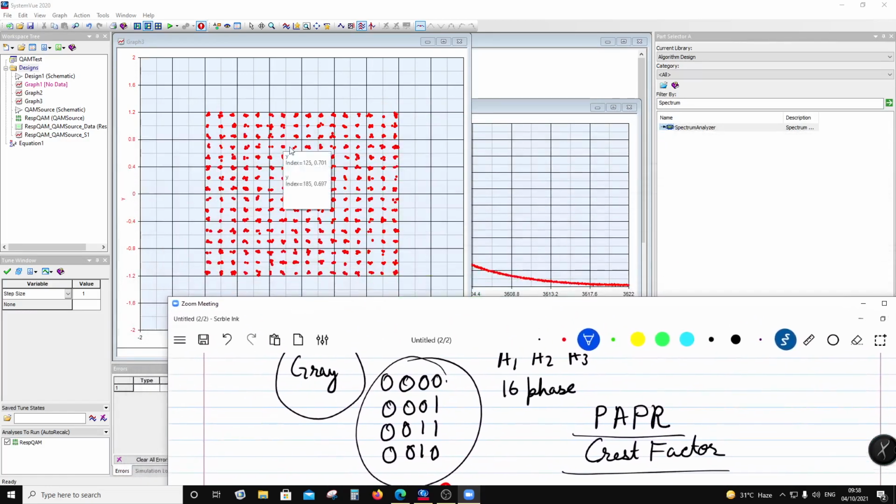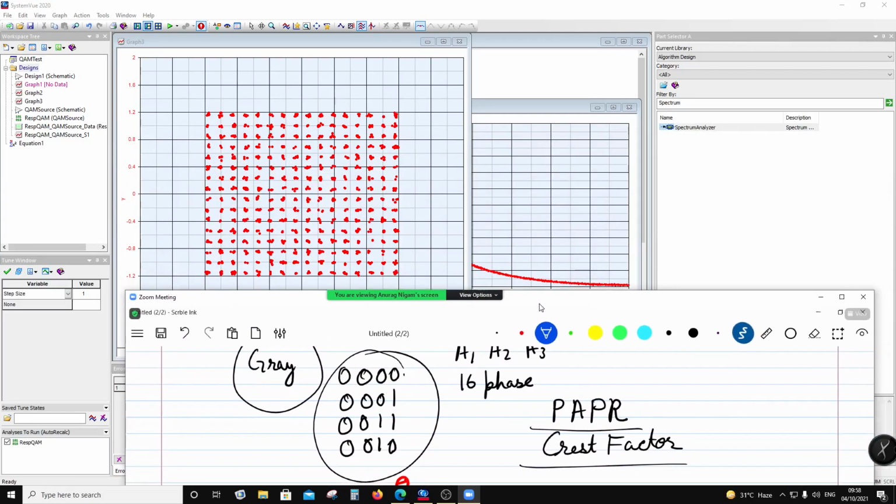So this is what you're going to transmit, QAM 256, and then it would go through your transmit receive chain, and it will also go through your channel, and these are going to add all your noises. They are going to skew this constellation, they are going to rotate this constellation, and when things go to compression, a non-linearity, they are going to move these bins all over the place, in the sense that you can see the effect once you put it through the chain, and I'll do that later on.